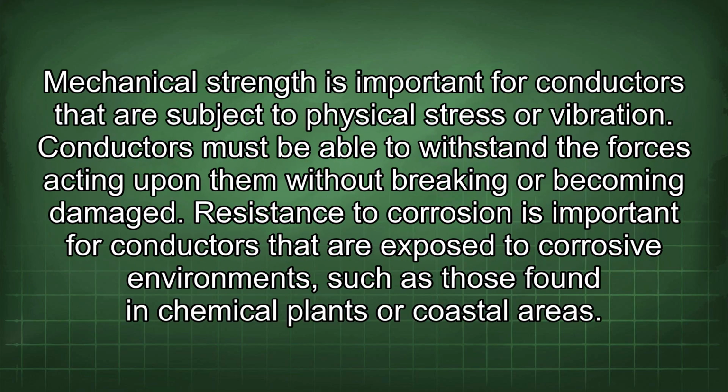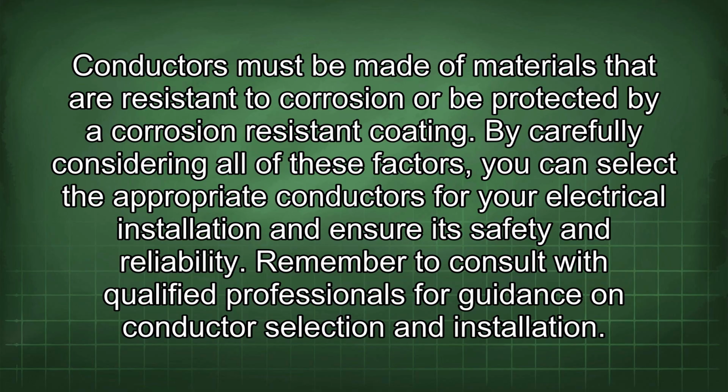Mechanical strength is important for conductors that are subject to physical stress or vibration. Conductors must be able to withstand the forces acting upon them without breaking or becoming damaged. Resistance to corrosion is important for conductors that are exposed to corrosive environments such as those found in chemical plants or coastal areas. Conductors must be made of materials that are resistant to corrosion or be protected by a corrosion-resistant coating. By carefully considering all of these factors, you can select the appropriate conductors for your electrical installation and ensure